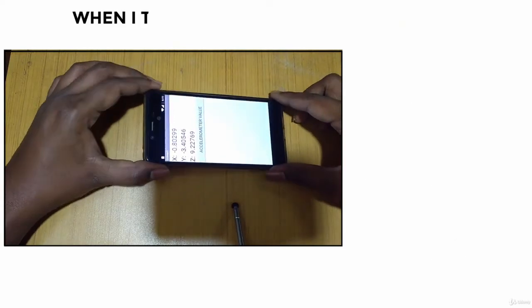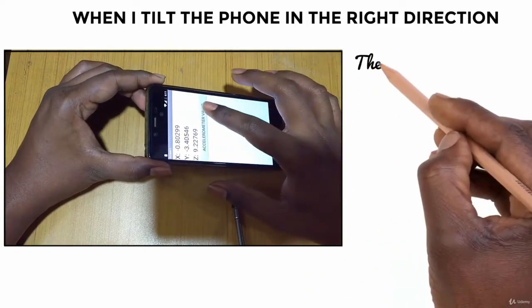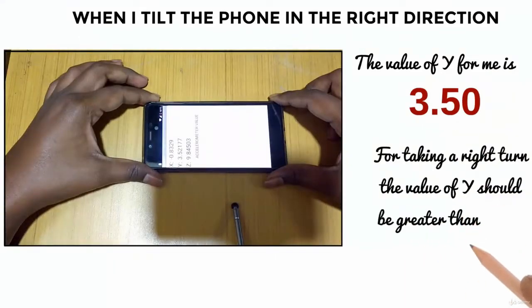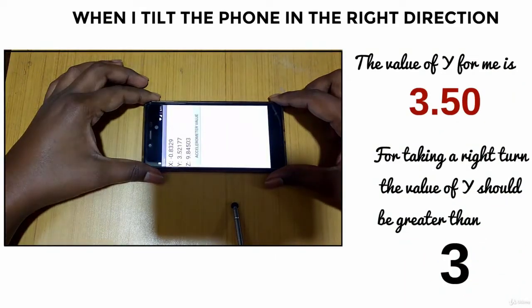If I tilt the phone on the right, then the value of Y is 3.5. So if you want your robot to take a right turn, then the Y acceleration value should be greater than 3, that is 4, 5, 6, etc.